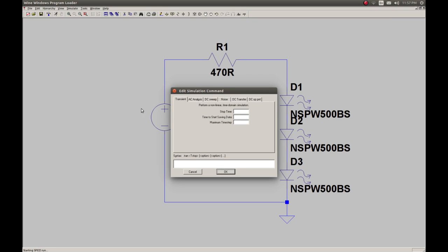So what I am going to do now is a DC sweep, where I can give a starting voltage and a stop voltage. I do a DC sweep because the battery which we are using in practical applications can decay very fast. So it asks for the name of the first source to sweep, which I give V1.